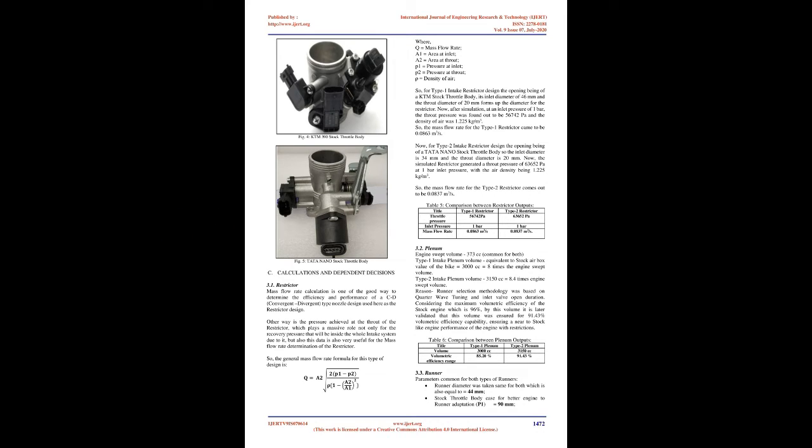In Type 2 of the intake manifold, the throttle body outlet diameter was calculated by the reference RPM method, and a similar or close to similar throttle body was found, and its internal structure was studied in a CFD tool, and also it was virtually simulated in Ricardo Wave with the already constrained manifold to find out the characteristic of the performance curve. Practically, Type 1 throttle body has enough diameter to saturate the restrictor within 50% of throttle opening.